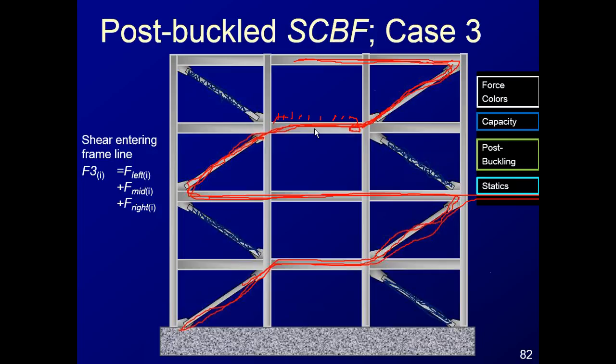If you have several bays of collector, let's say we look at this load path, maybe you can throw a lot of the load into the deck here and get it out of the deck over here, and maybe that takes some of the heat off of these two connections. So depending on what your situation is, it might be easy or not so easy to engage that composite deck as part of your system, part of your collector.